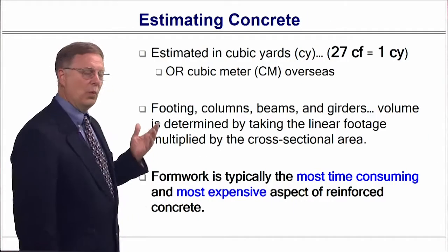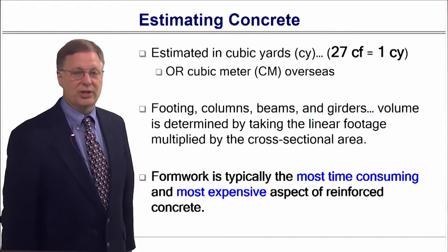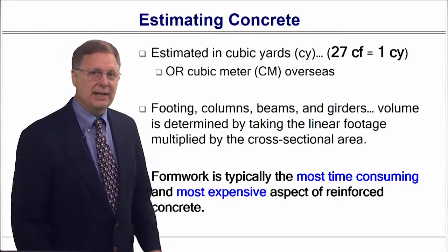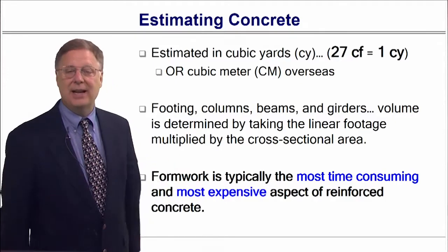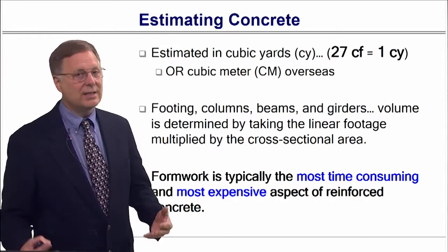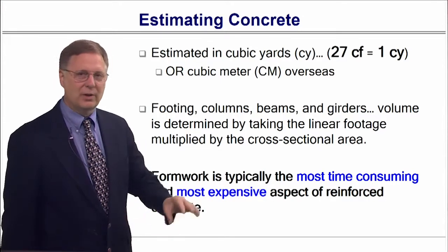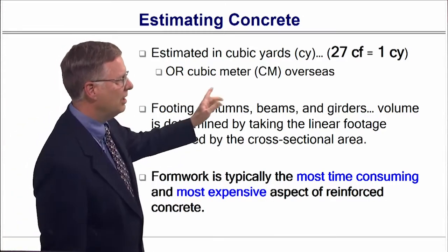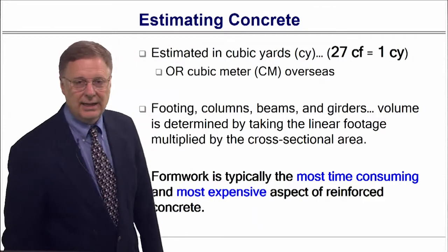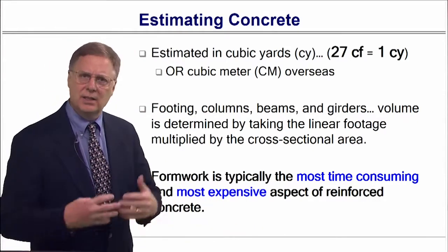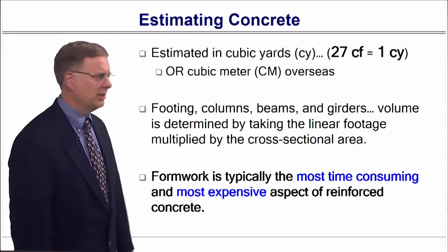All right, the way you estimate concrete is in cubic yards, just as we did with the excavation, and you have to know that conversion. Just get it in your head and stick with it, because in the U.S., that's how we operate. We work in cubic feet and convert into cubic yards. I know overseas you'll deal with cubic meters, and I doubt that we're going to be measuring things in centimeters, but nonetheless, you need to know how to convert those things around as well.